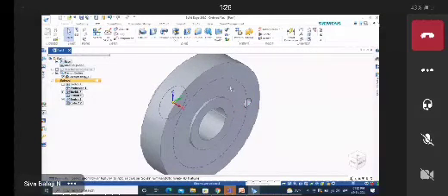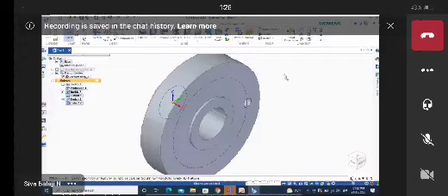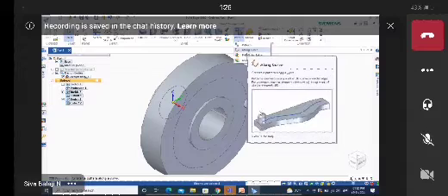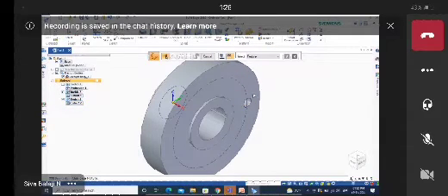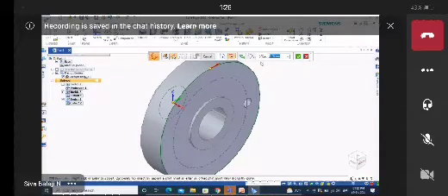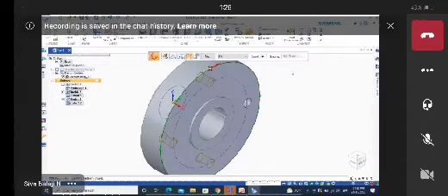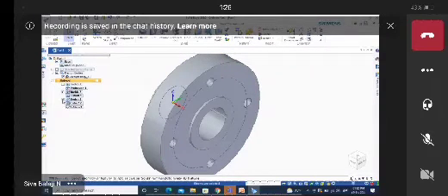Okay, finish, cancel. Now the remaining 3 holes are required, so you can go to the pattern command. In the pattern command you can select along curve. Along curve, select the feature. This is the feature. You can accept that feature and select chain. Now you can accept that one. Okay, for circular objects there is no need to give an offset angle, because it is a circular object and the spacing is already there. You can accept that. He's asking for the count. You can give count 4, then next, preview, finish. Now flange one is completed here. You can check it here. Flange one is completed.